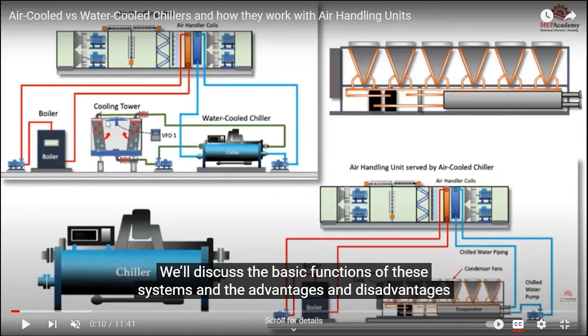It has other issues. For example, if it's in contact with potable water, in a cooling tower there is a lot of bacteria, and if we end up drinking this water that comes from the cooling tower, we can have health issues. So cooling towers work well in these non-potable water circuits, because nobody drinks the water that goes from the cooling tower to the water chiller. But if we have a cooling tower in a circuit that is in contact with water that we can drink, we can have some issues.